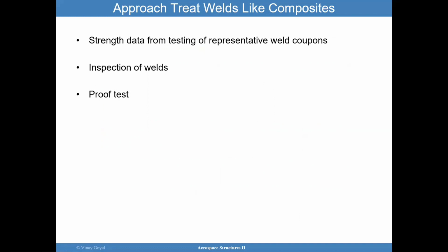But I think you need to pay attention to the testing and learn about what your welds are doing to the heat affected zones, where the samples are failing, what kind of residual stresses you're putting in them, and then do a lot of destructive testing to make sure you have a repeatable quality of that weld, but also look for porosity, cavities, cracking, and all the things we talked about. These samples can be quite beneficial too.